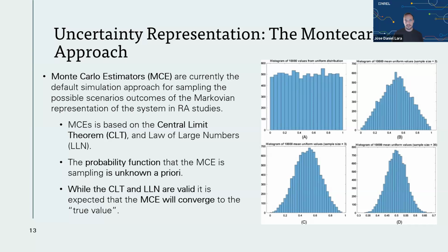In the classical central limit theorem, it doesn't matter how many simulations I run, I might not be able to capture these types of extreme events, both because of the correlation and the rarity. So we have to understand the limitations of Monte Carlo approaches when it comes to capturing situations that don't happen very often. I think one important component of resource adequacy is to have this discussion with the stakeholders about how far we can take an analysis that employs Monte Carlo to have some security about our system's properties. We're going to go to the next slide.